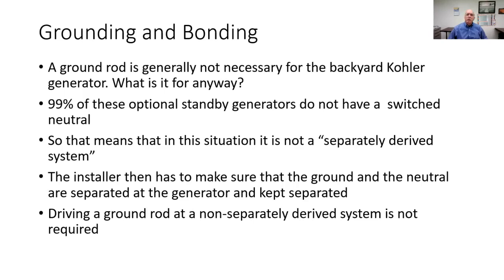99% of these optional standby generators I mentioned do not have a switched neutral. So that means they're not separately derived systems. The installer has to make sure that the ground and neutral are separated at the generator and kept separated.